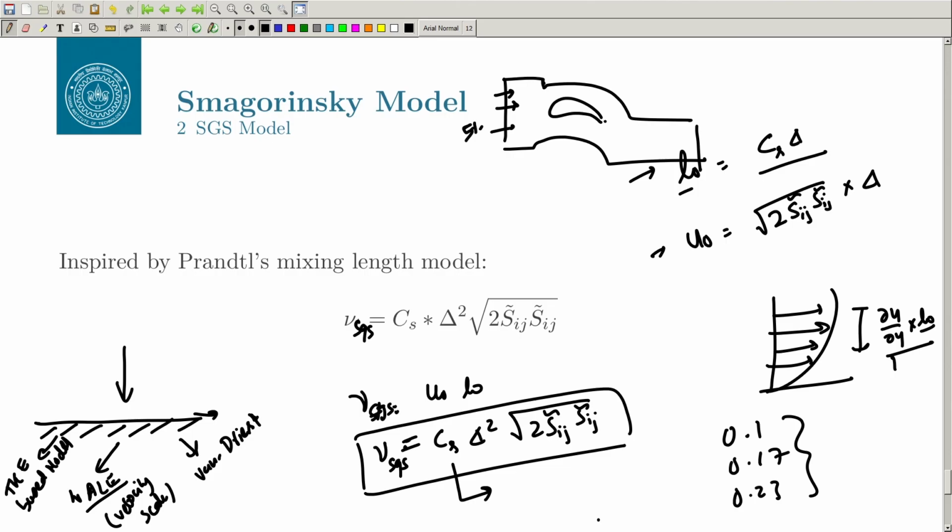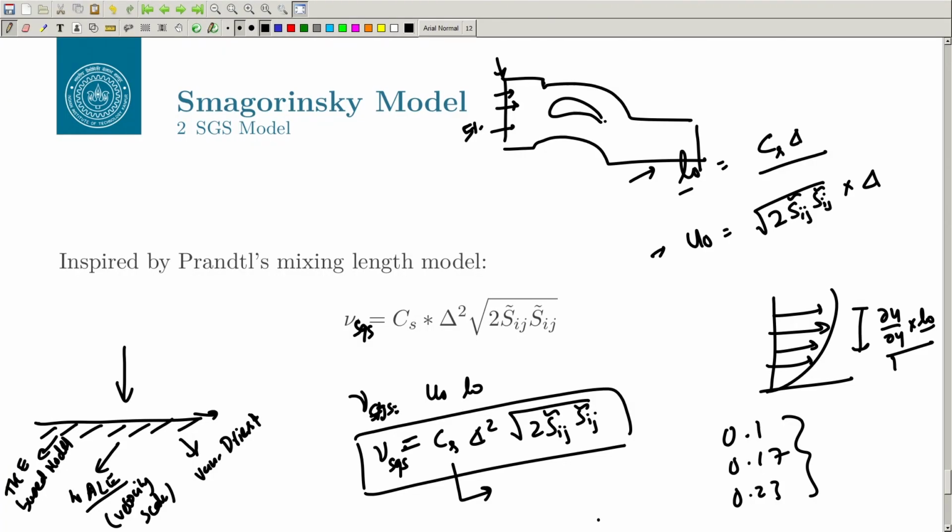So, you cannot give an integrated quantity. You cannot give, let us say, turbulence kinetic energy or the dissipation rate in the beginning. What you need to give is your u prime, v prime, w prime, rho prime and p prime and so forth. You need to provide the fluctuations in LES or a DNS. It is a very important thing, because if you do not provide this, then essentially your incoming flow is laminar, and for it to develop turbulence, it will require a very long length, and typically you cannot afford those kinds of things.